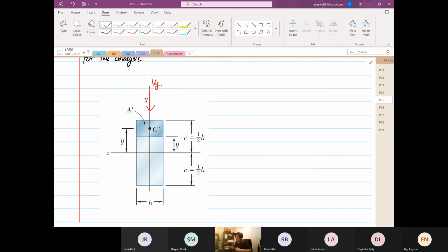So for this case, the area starts from the furthest away from the distance. This is the start of the area. Y is your slider. You decide where you want to stop. It's a variable, so over here, this is the end of the area of interest. Now the formula again is the shear stress xy is equal to shear yx is equal to Vy over Izz Qz t.